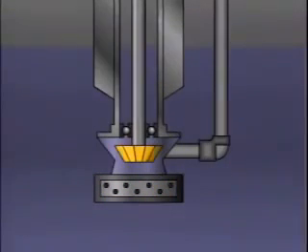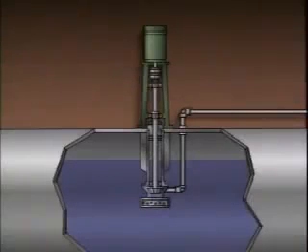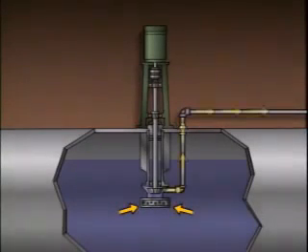The pump's impeller is also submerged in the liquid. This helps to ensure that the pump is always primed. This means that the casing is filled with the process liquid. During operation, liquid is drawn in through the suction and then pumped through the discharge piping, which extends up and out of the tank. All centrifugal pumps work by creating a centrifugal force.